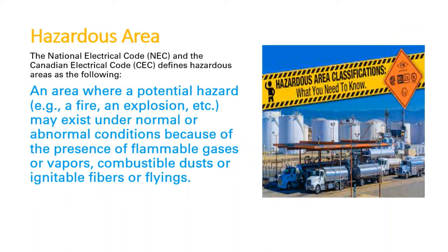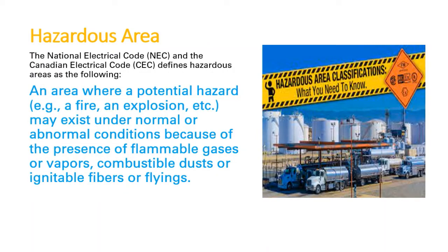As per NEC and CEC, this hazardous area is defined a little bit differently, but the main concept is the same. This is the area where potential hazard may exist under normal condition or abnormal condition because of the presence of flammable gas or vapors or combustible dust or ignitable fibers or flyings.